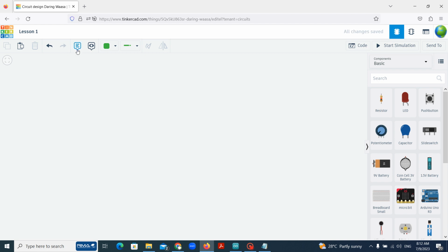Okay, here is a comment. For example, if you want to comment on a resistor, because if we have a lot of components, we cannot see the value of the component. For example, I put 100 kilo, and I put the note on this resistor as 100 kilo.